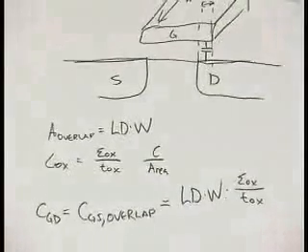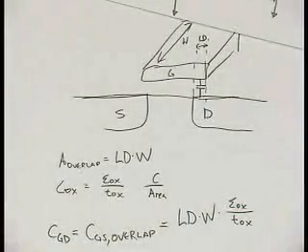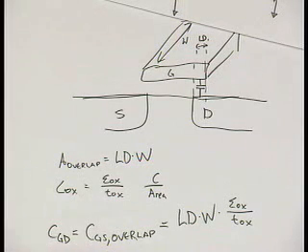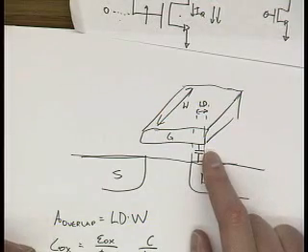Yeah. I'm just kind of curious, in an analog process, do they do anything, since that Miller capacitance is devastating, do they make any effort to shift that overlap away from the drain? There's no such thing as an analog process when it comes to CMOS because 90% of CMOS is digital. So the reason why you can use analog and it's so cheap is because you're piggybacking on a digital process. And this does affect the digital guys as well. And there really isn't anything you can do about it because it comes down to the way the devices are fabricated.